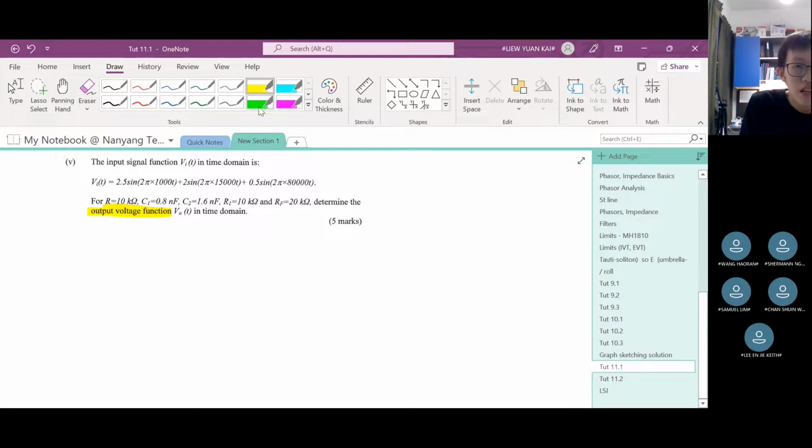So how? This question tests your understanding of the practical use of the op amp. Now, because there are different frequencies, what does that mean? And above just now, we have identified that some of the stages act as a filter. Don't forget that some of them were filters, correct? And then now we have different frequencies. So what will those filters do? They will block out some of these waveforms.